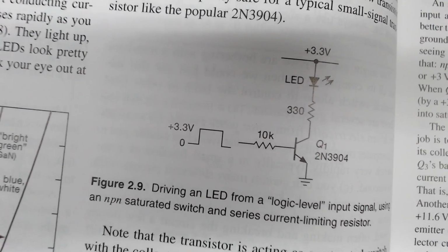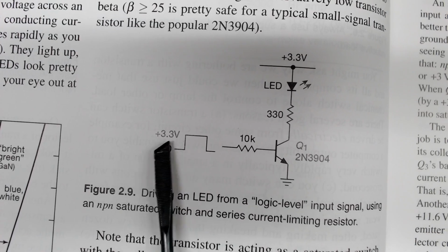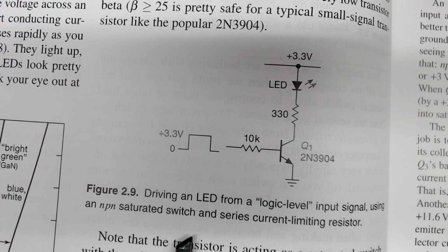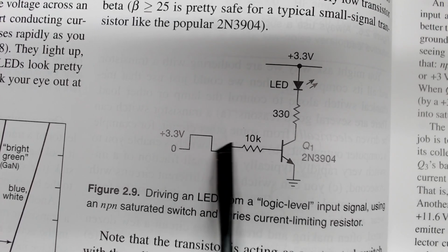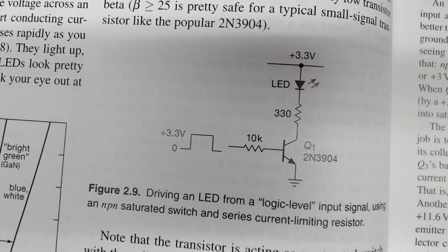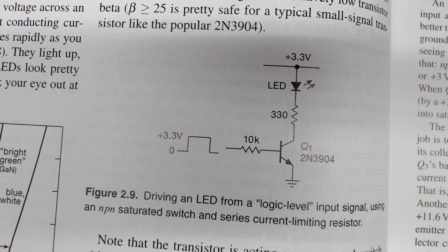And so here's another really good example of a transistor circuit actually happening. We have this 3.3 volt signal, and this is a square wave, so this is just going to go on, off, on, off, on, off through this resistor here. So we're drawing a bit of a current here, which is causing a much greater current to flow through here and light up this light. That's the idea. That's the core of what we're trying to do and what a transistor is essentially doing.